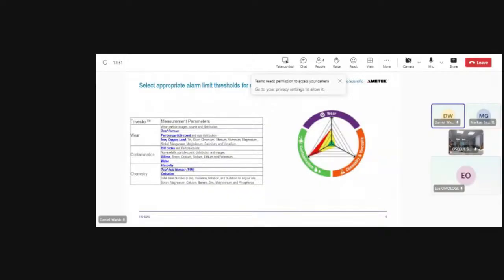For example, in a rotating machine such as a turbine, everything that you see here in blue would be the parameters you would pay particular attention to first, because those are the most likely to indicate a problem before the other parameters. So rather than alarming everything, you would alarm those and focus on those initially. And that's what's quite common.